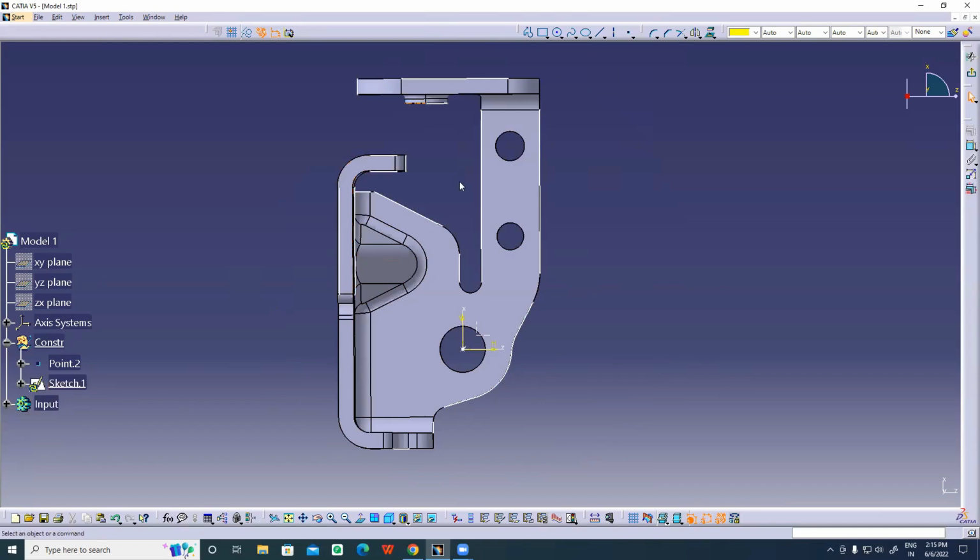Oscar, you said you will be projecting the straight lines, but here in the bottom, you selected a curved surface. Yes, because in this portion there is no straight line available, right? I want this portion to be projected. So since there is no straight line, I simply selected the curvy portion. Wherever we have this tangent curvy portion, these are straight lines, right? I'm going to trim it. It will become like this corner, right? After that, I will be applying a fillet. Since there is no straight line in this portion, I directly projected it and I'll be applying a radius to that.